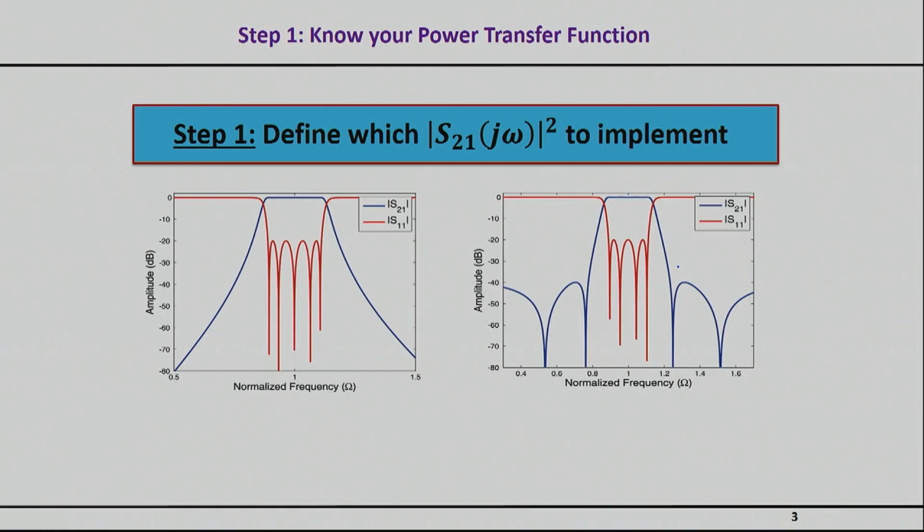In a previous discussion, we talked about how one might select this type of transfer function. They're primarily determined by characteristics related to amplitude and phase. And as I mentioned before, in this class, we're only going to be defining transfer functions based on amplitude. So essentially, it's the S21 as a function of frequency squared that we are having here.